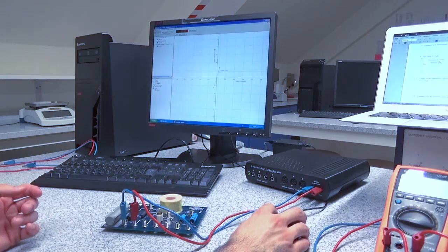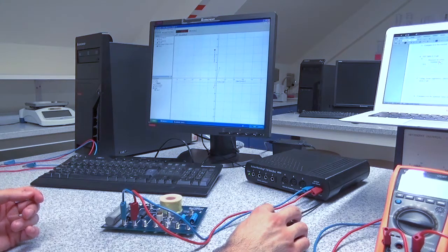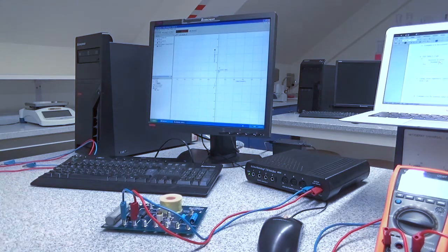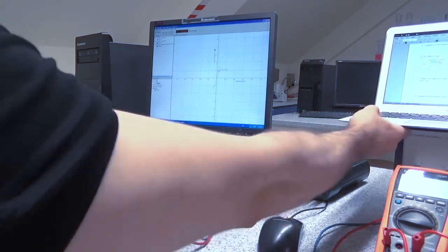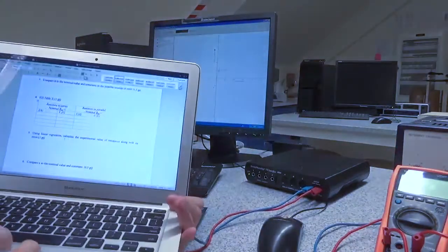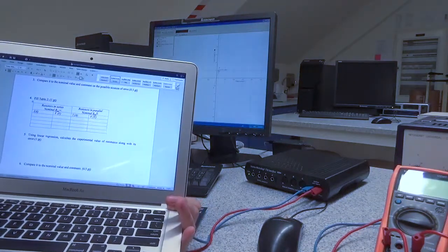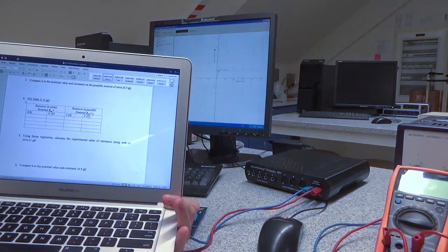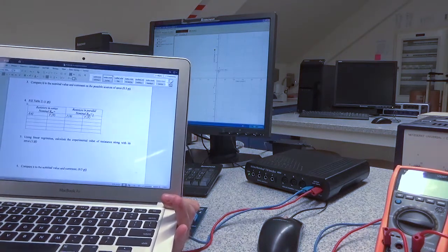And in a similar manner, you are going over here to slide that XY coordinate delta tool across that straight line in order to pick 4 different points for the voltage and the current, for which you are going to apply all over again linear regression in order to find their slope and the error on slope. And then in that same part over here, they ask you now to connect both resistors in parallel, but first off, you need to find their nominal equivalent resistance.